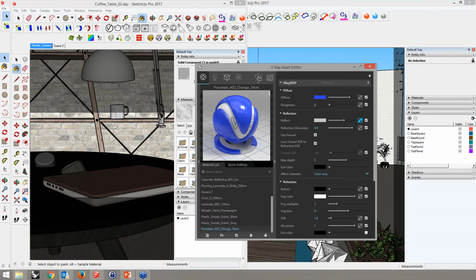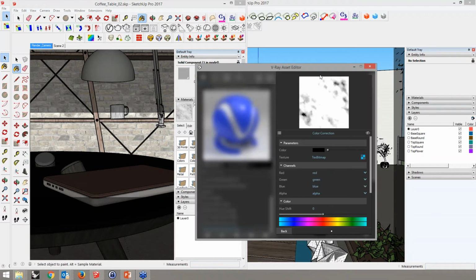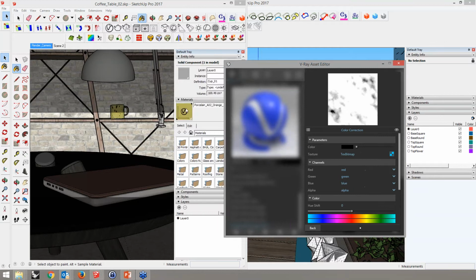So you actually choose which texture you want to show up here by going into the material. Right now I'm using this, I can use this texture simply by selecting this. And this is really just a placeholder, and you'll notice inside SketchUp itself it's using a placeholder texture, so you can make sure that your texture sizing is correct. It's kind of hard to quickly explain this. Feel free to reach out to me after the webinar, but it's a placeholder inside SketchUp, and when you hit render, it will come through as the correct material.